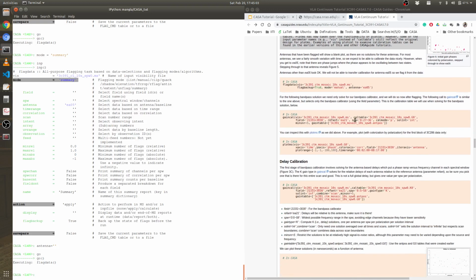Okay, so let's go for the first calibration we want to do. Before the bandpass calibration, which is for frequency, we want to correct for frequency, right? So first do the time and delay. Otherwise, if you don't do time and delay first, then they will create more calibration problems before the frequency. So you have to correct first for time, then frequency. The delay is also a time delay, so you have to correct for that also. So we'll do the time thing. Okay, let's do it fast.